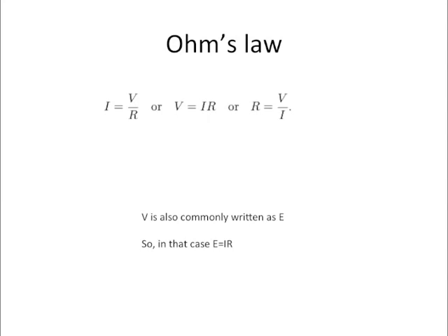So we can use Ohm's law, which I learned as E equals I times R. You could write out voltage as either V or E, but basically know that all these things are relative. If you know what your voltage is and what your resistance is, then based on just those two things, you can figure out what your current is going to be by taking the voltage and dividing it by the resistance.